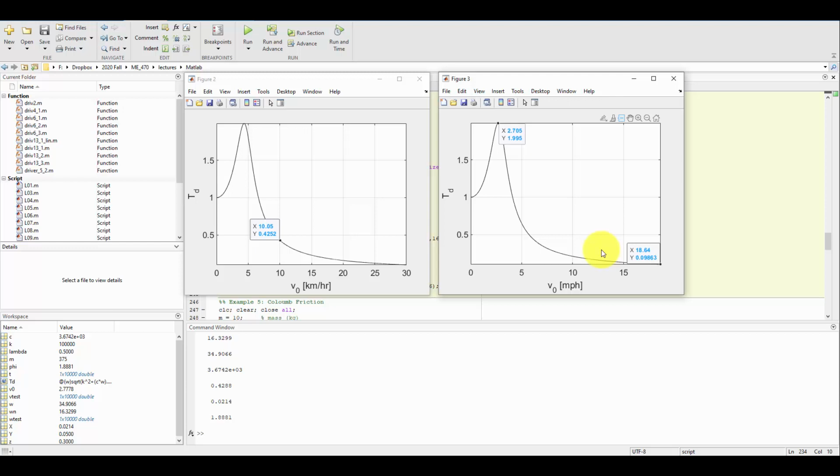So we would want to look at this total solution of our displacement at various speeds, not just the steady state, before we decide it's a good idea to go faster over the washboard road. Also, our only judgment of smoothness of ride here is the amplitude of displacement of the cabin. That might not necessarily be the best measure of the smoothness of the ride.